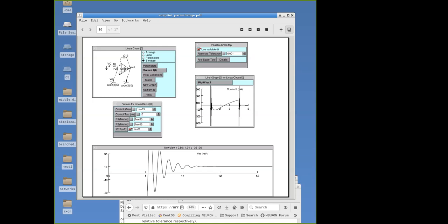In a real situation, amplifiers always have maximum limits on the rate of slew of their output potential, the speed with which their output voltage can change. And also, there's a limit on how fast a signal they can follow, period, even if you stay within the slew rate. This is imposed by built-in capacitances and inductances in the integrated circuit or whatever other circuitry you're using, and there's always stray capacitance. And so by attaching this little tiny capacitor between the inverting input and the output, we stabilize it a bit.